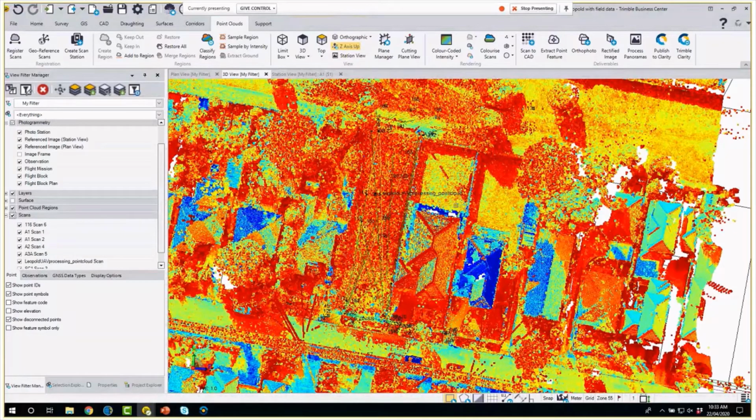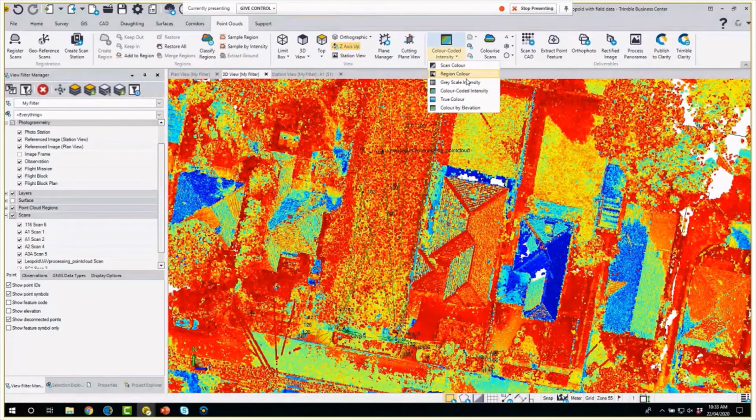What we can leverage here from a design aspect is that TBC has an ability to export SketchUp files, and we could do some designing in here or house placement to be able to more easily figure out what the overshadowing problems are.